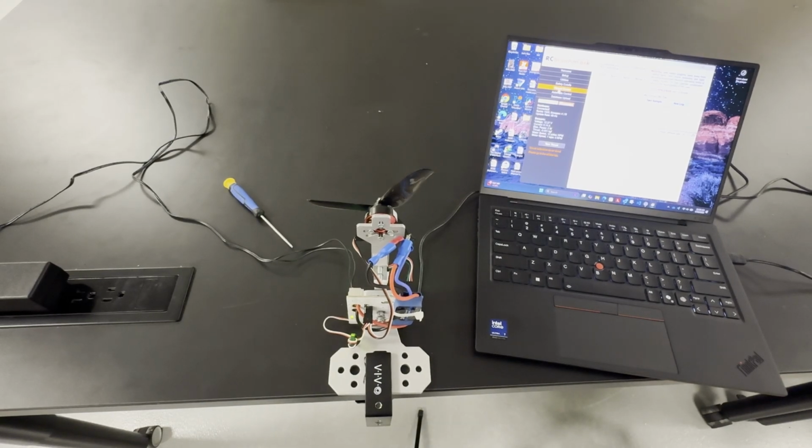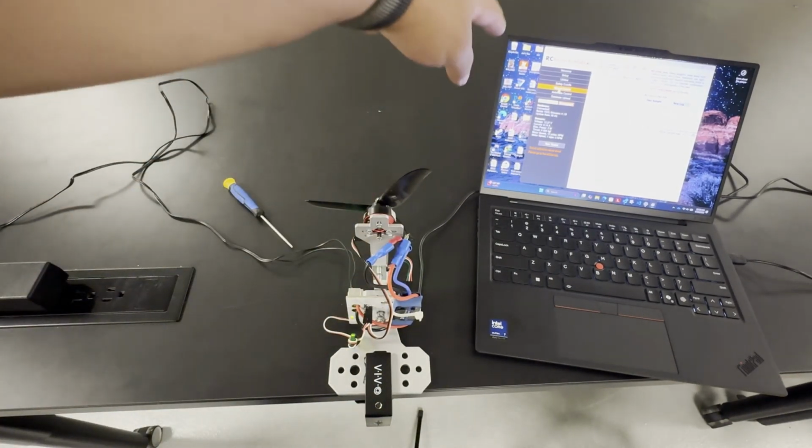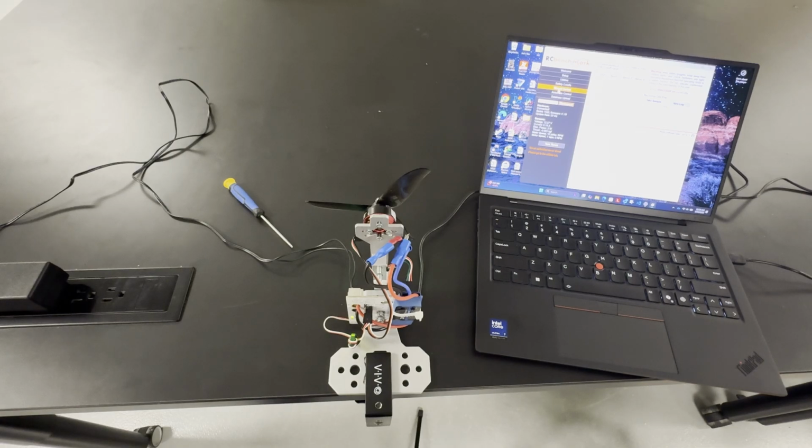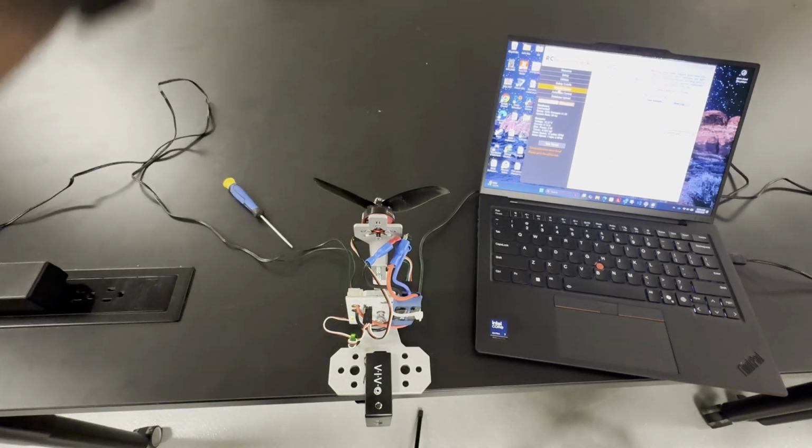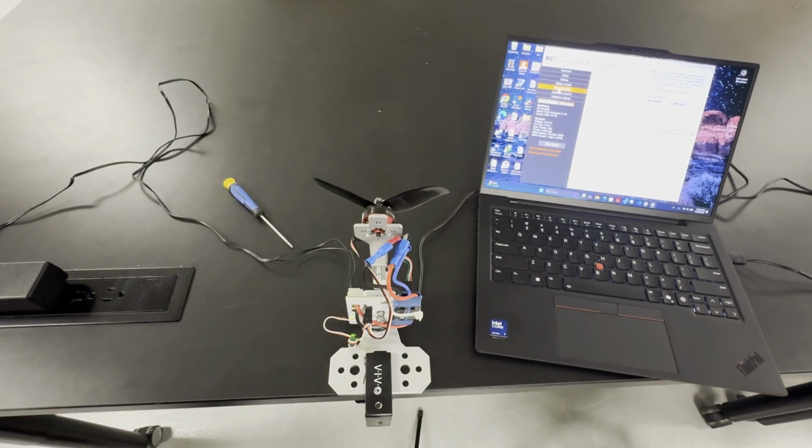This is our setup. We have the power supply, we have the thrust stand, and we have my laptop and software. The software is called RC Benchmark. It has a very intuitive GUI, but there's an order to setting this up. You want to make sure that this is connected to the power supply first, and then connected to USB. The reason is USB itself can also provide power, but the power is not enough to run the thrust stand. So you want to make sure that you provide power first and then connect the USB, so that you have a connection to your laptop and you can read the data off of the thrust stand.